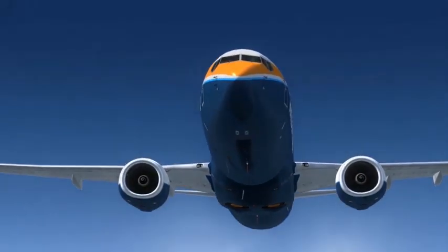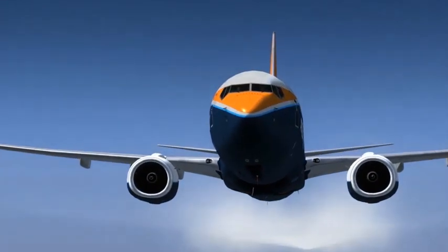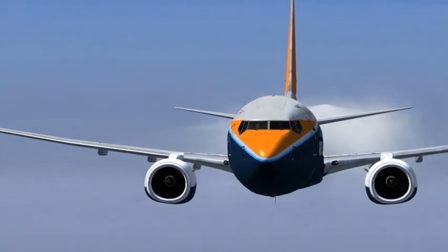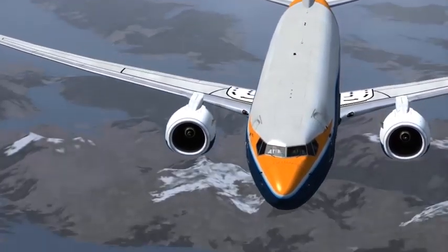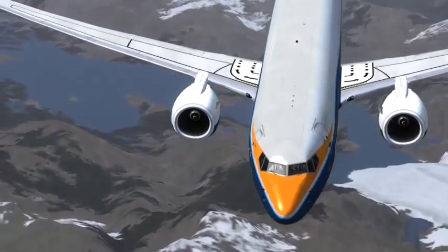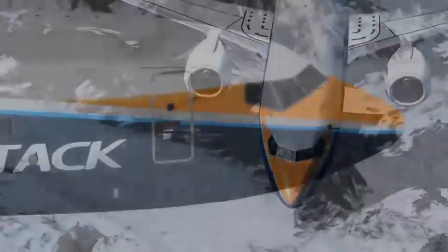If at any point the cabin altitude increases past 10,000 feet, a cabin altitude warning horn will sound. To extinguish this horn, the Alt Horn Cutout button in the cabin altitude panel must be pressed.